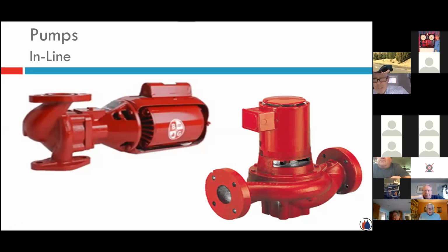But a lot of times, the mechanical room might not be lit up or as accessible as you'd like. So just a quick little note, if you can't find that arrow, but you can see this hump, this bump on the volute, the wet end of the circulator, that's an indicator that the flow is moving down into this hump or bump and into the eye of the impeller. Same thing over here. It's moving in this direction into the eye of the impeller, being discharged out the discharge port.